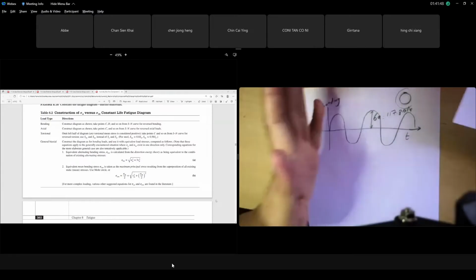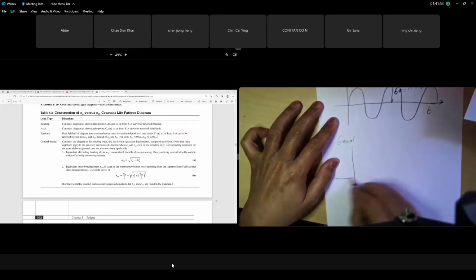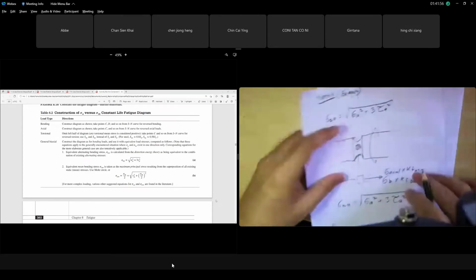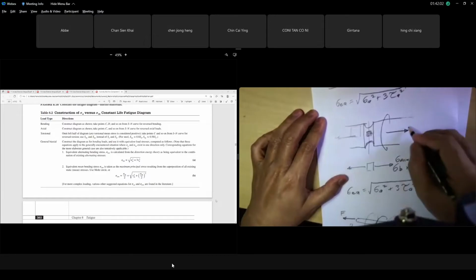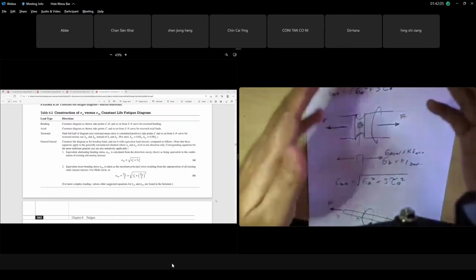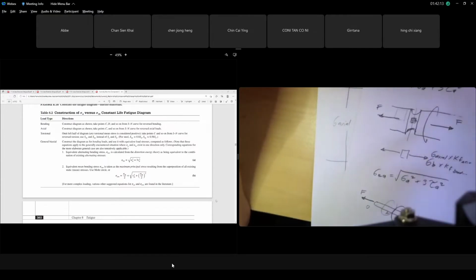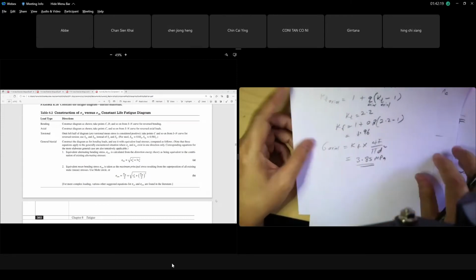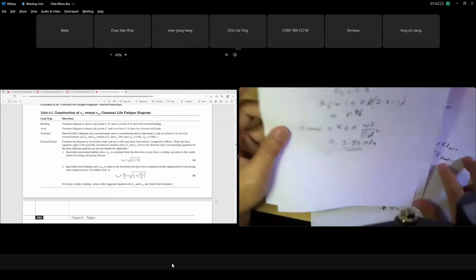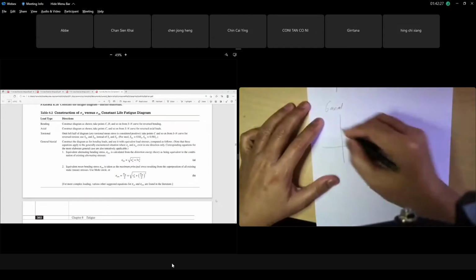Okay, that is bending. Remember at the notch we also have axial. Sigma axial. What about the axial stress plot through time in this case? This is your shaft, this is your notch. You have axial force. Now you have axial stress. Just now we calculated sigma axial as F over pi d squared times KF axial. The value we calculated just now was 3.85 megapascal, after multiplying by KF axial. So our axial stress is 3.85 megapascal. When plotted against time, will the axial stress be a sine wave or a straight line?